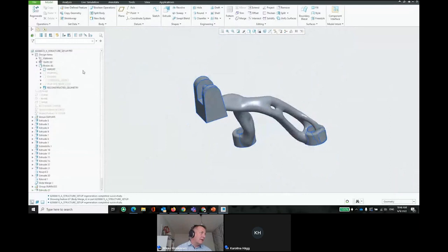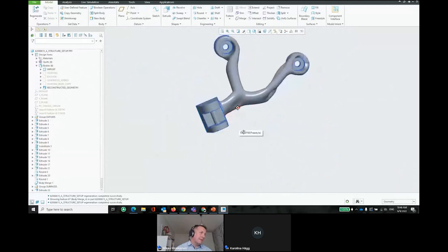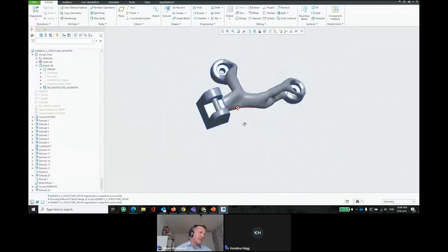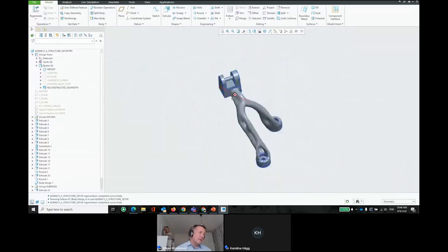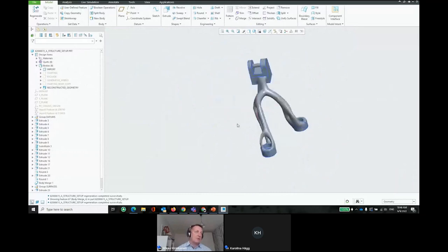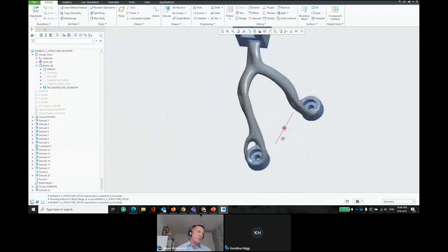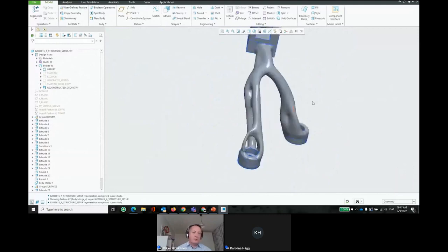If you have more limiting manufacturing methods like sheet metal or something like that, then you could also consider that if I weld a piece like this in here, then I may just have to use an arc-shaped piece of sheet metal, which has a constant thickness, of course. Or if you want to mill it from above, then you just basically neglect all the voids in here. So it's a starting point for your geometry optimization.